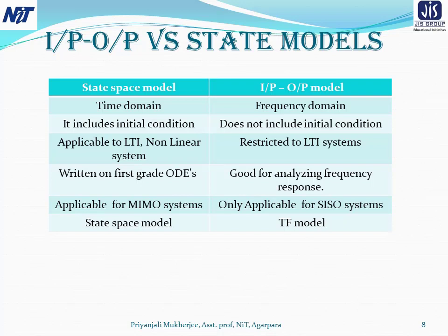In the state space model, we can apply the model to linear time invariant, linear time variant as well as nonlinear systems. But the transfer function model is restricted to linear time invariant systems. And when we write the state space model, it can be written as first order ordinary differential equations. An input-output model is good for analyzing the frequency response.